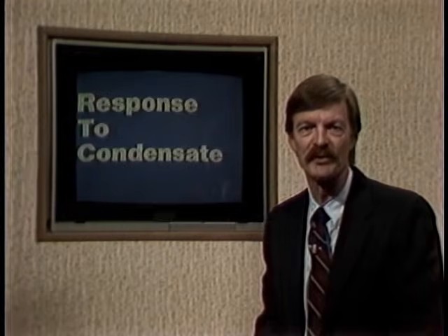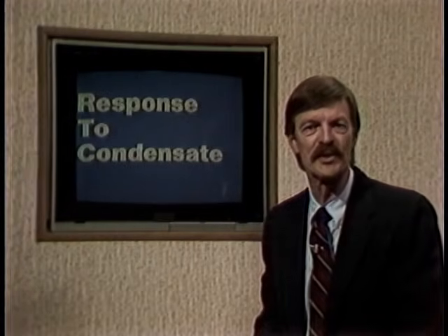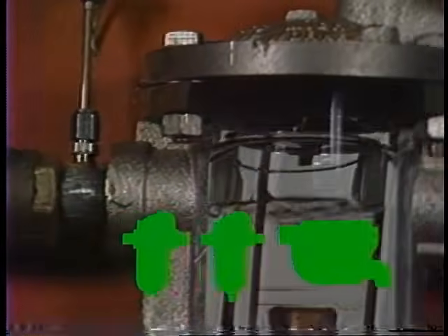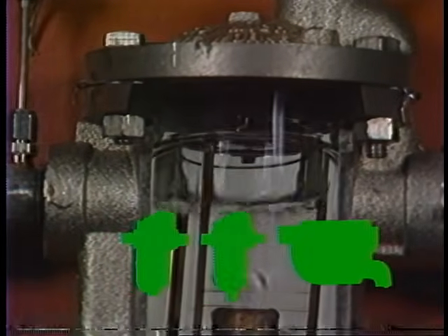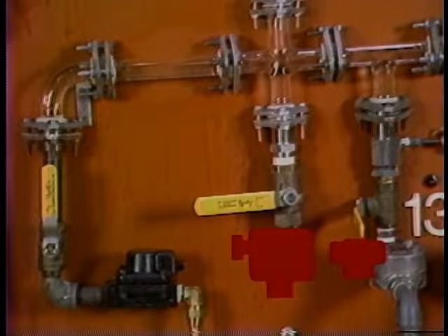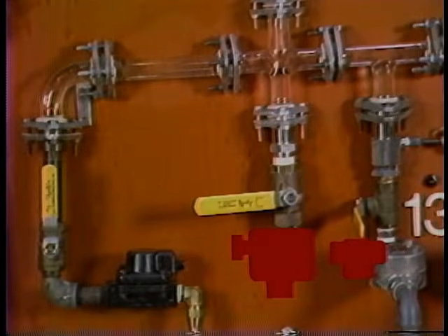The operating principles of each type trap determine the nature of its response to varying condensate loads. The mechanical traps, the IB, DC, and F&T, are continuous drainers. They are controlled directly by the amount of condensate entering their bodies and therefore respond immediately to any load changes. Thermostatic and thermodynamic traps react to changes of temperature or changes of state rather than responding directly to the presence of condensate. All traps are required from time to time to handle the heavy air and condensate loads of startup.